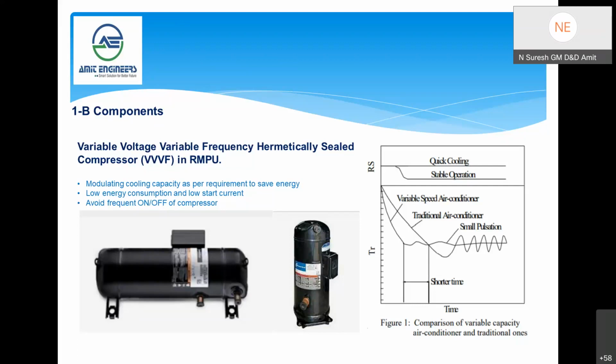What is the POH periodicity for these compressors? Like when they are to be overhauled or removed? I mean, what is the life or overhauling cycle? Sir, minimum 8 years or even more, our units are running in the field. In the vertical scroll, we have been supplying to Indian Railways in LHB coaches. With proper maintenance, the reliability will increase and the life of the compressor will increase.